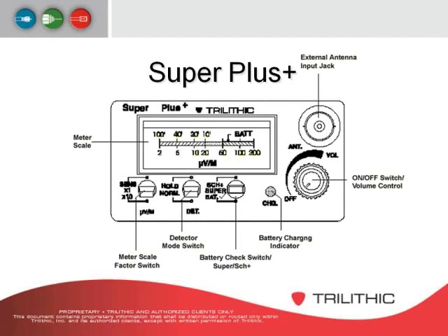At the very far left, you'll see a sensitivity button. That's the scale. If it's on a ×1, then what you measure is what you get. So if you're looking at the meter scale, if the needle was pointing at 5, then it's 5 microvolts per meter. But if you put the ×10 on there, then instead of that being 5, it's really 50 microvolts per meter.